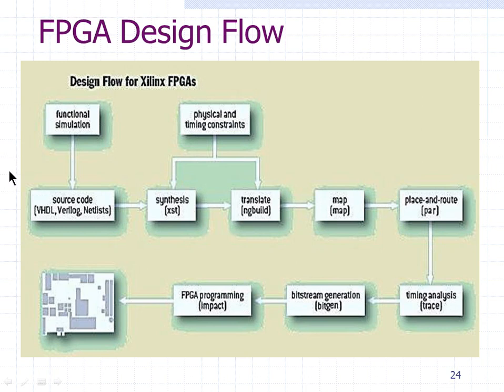The part which needs to be implemented as a chip will come here as a design specification. Then you or a team of engineers will start writing Verilog code for that. Let's say you are given a small block to design. For that block, you know what needs to be implemented, as there is a very clear document that talks about that. You will start writing Verilog code for it.